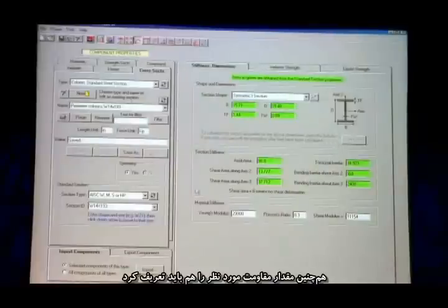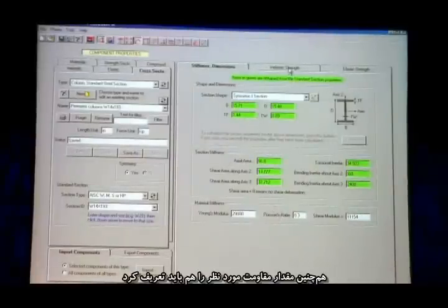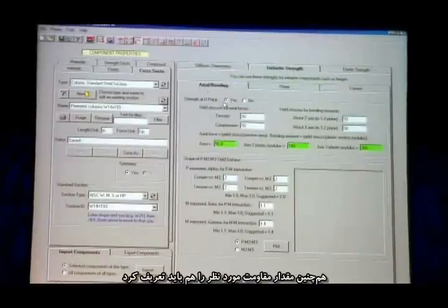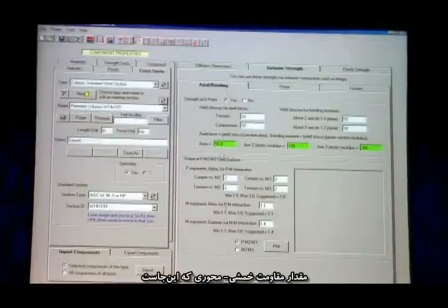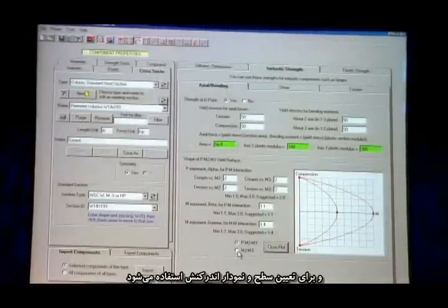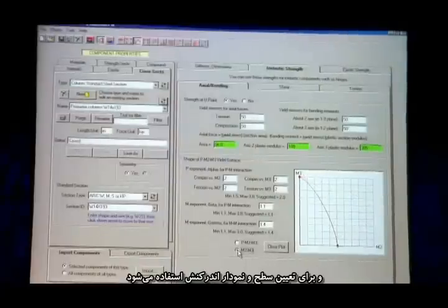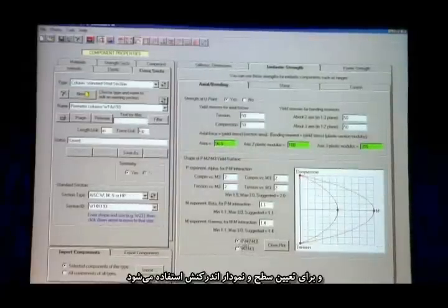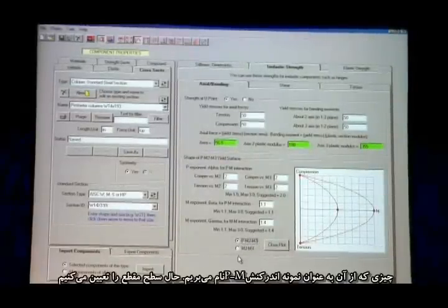You specify the cross-section, and these now are the section properties, but you can also assign a strength to these things. And what I've done here is assign some axial bending strength, and this means that there's an interaction surface, not a hysteresis loop. So this now is a column with a PM interaction surface, and I've specified a cross-section.